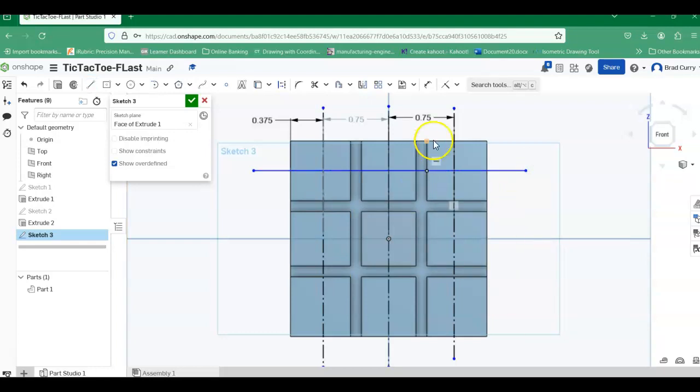Notice this came in as a solid object line. So that's not a big deal. If I just come back up here to the construction line and click on that, or click on the line and then go to construction line, it will turn that line into a construction line for us. So let me hit the escape key here, or left click out here, so we got that placed. Let's go ahead with another one.